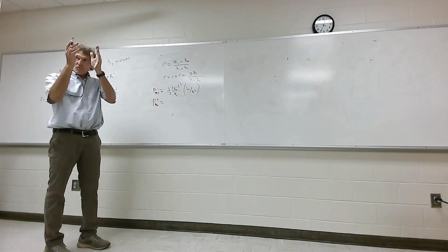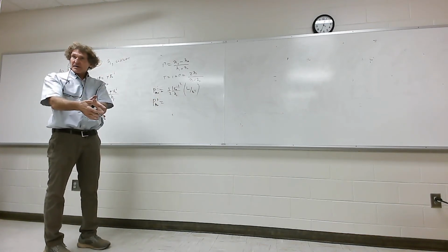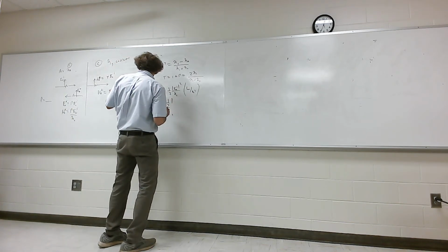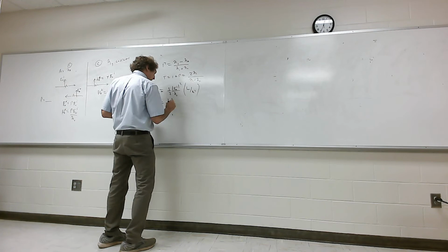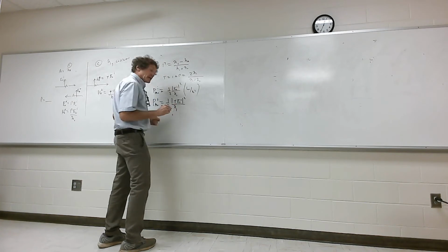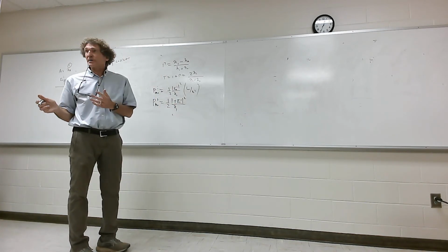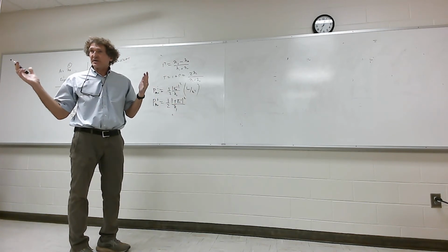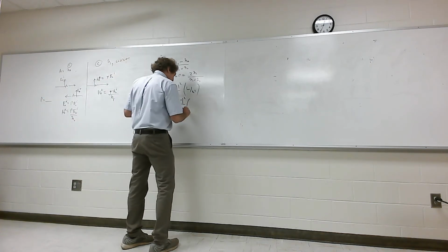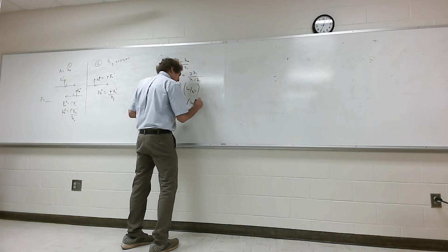It's the same form, 1/2 E squared over eta. So it's going to be 1/2, my E over here is now the transmission coefficient times E0 incident, squared, over eta 1. It's important, because I always see the eta values get messed up. They will use the wrong value. And that would be in watts per meter squared.